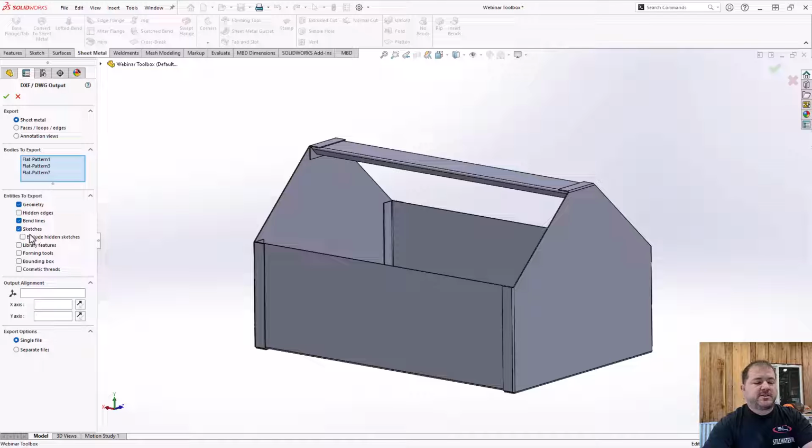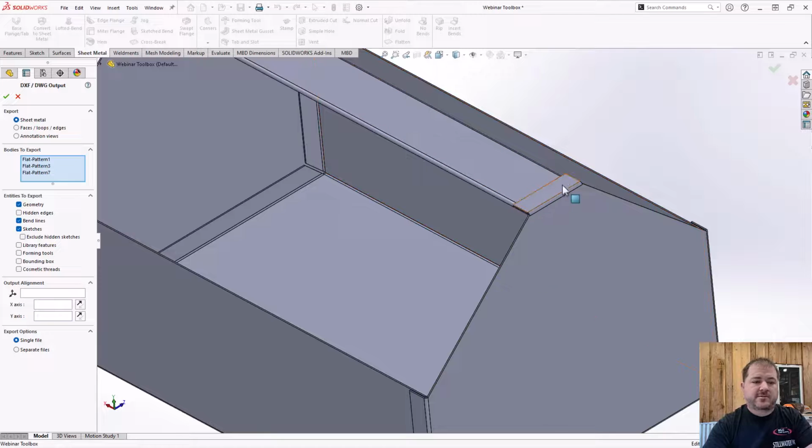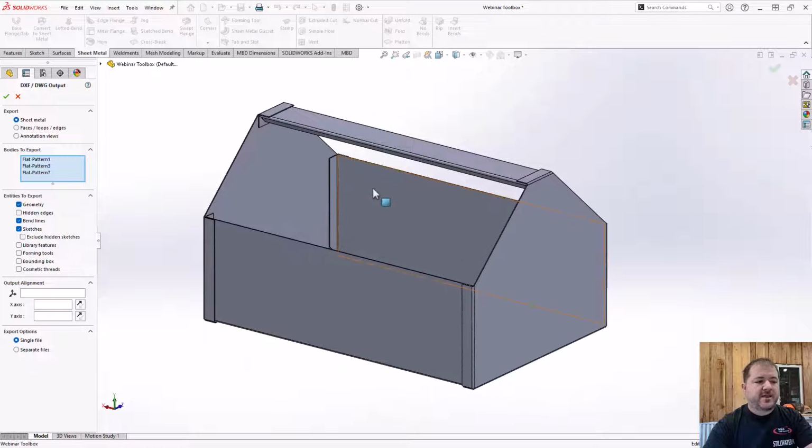Now these sketches, this is where you might put in like a scribe layer, right? You may want to scribe your bend lines. You may want to scribe a logo or some targets for drilled holes later, or locations for some things. Right? Maybe you want to document where you want your spot welds to be. You could scribe a little X or something like that. Everybody's got their own way of doing things. If you want to put that in there, you can. I'm going to say I want to put them in as separate files, but I want to be careful about how that gets exported.